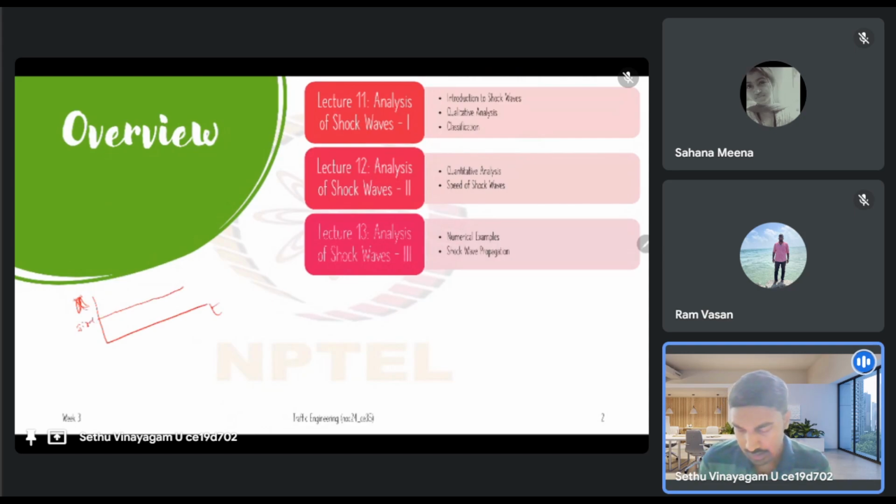So what happens in a signalized location? For a certain duration you have green time, so vehicles can pass through, and for a certain duration you will have red time, in a cycle. When vehicles can't pass through, you are creating a different traffic state forcefully, right? Let us assume this particular region is your red duration. Initially some demand is there, so the inflow into this signalized location is some value A, some traffic state A. Vehicles will be passing through without any interruption, so this has a traffic state of A.